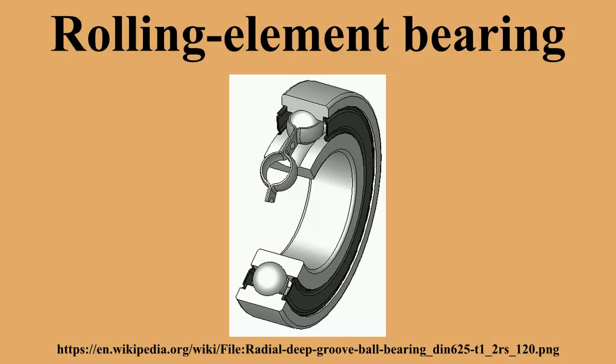Often the ends of the rollers taper to points, and these are used to keep the rollers captive. Or they may be hemispherical and not captive but held by the shaft itself or a similar arrangement. Since the rollers are thin, the outside diameter of the bearing is only slightly larger than the hole in the middle. However, the small diameter rollers must bend sharply where they contact the races, and thus the bearing fatigues relatively quickly. Carb toroidal roller bearings.